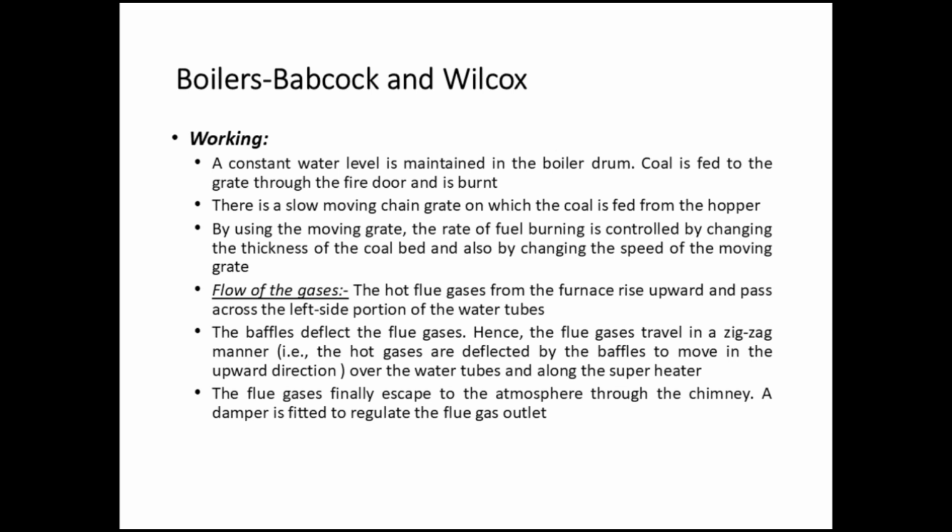Flow of the gases. The hot flue gases from the furnace rise upward and pass across the left side portion of the water tubes. The baffles deflect the flue gases. Hence, the flue gases travel in a zigzag manner. That is, the hot gases are deflected by the baffles to move in the upward direction over the water tubes and along the superheater. The flue gases finally escape to the atmosphere through a chimney. A damper is fitted to regulate the flue gas outlet.